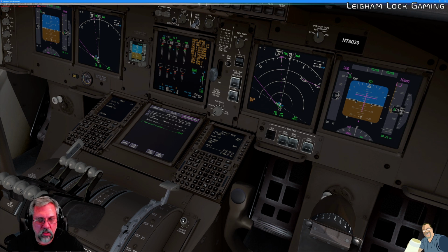Now that's one way to do it, and that's a bit of a chore. It certainly seems easier to interact with the page directly. Well, you can still kind of do that. The only catch is when you're looking at this EFIS control or ECAS control page, you can now roll your mouse on the page, and that does the same thing as spinning this dial by moving the purple highlight around. The one thing that they want you to do in the FCOM is go ahead and click on resets. So once I've got a button that I want to click highlighted, I can then just click anywhere on the page, in fact, and it will activate that button.